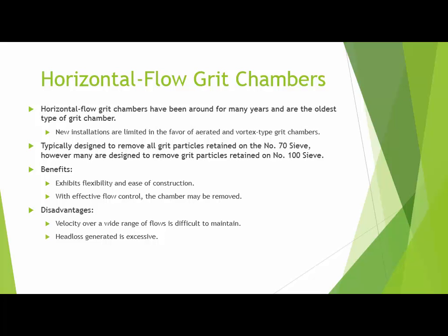Some of the benefits of the horizontal flow grit chamber are that it exhibits flexibility and is very easily constructed, and with effective flow control, the chamber may be removed. However, there are some disadvantages. Velocity over a wide range of flows is difficult to maintain, and the head loss generated is very large.